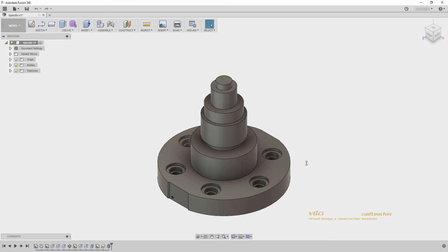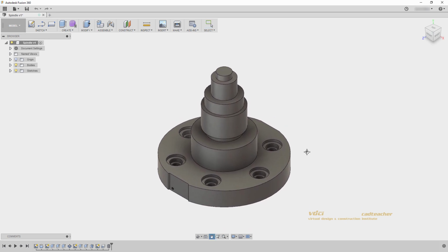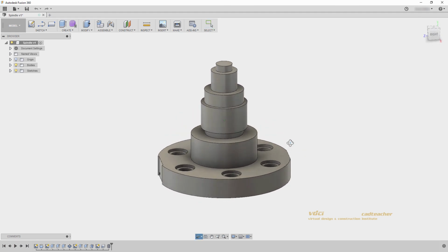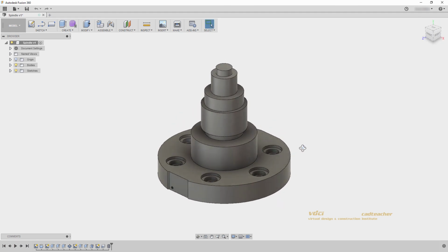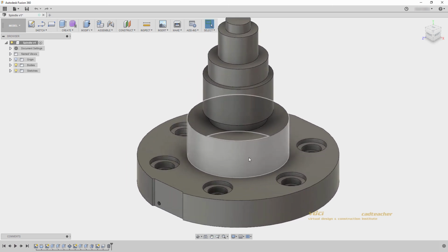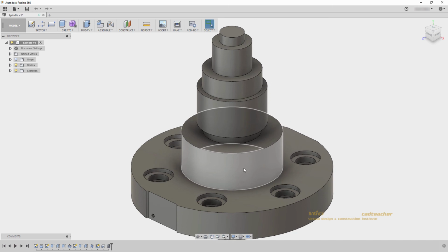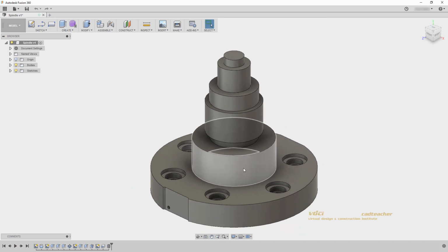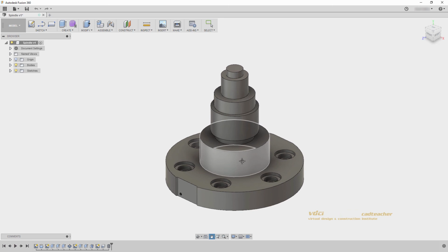Additionally, if you are working with a standard 3-button mouse, clicking and holding the middle mouse wheel will pan your model. Holding Shift and clicking the middle mouse wheel will orbit your model. And zooming is performed with the scroll wheel. So zooming the wheel towards you will bring the object closer to you, and you will zoom in. And scrolling the mouse wheel away will move the object further away, and will zoom out.